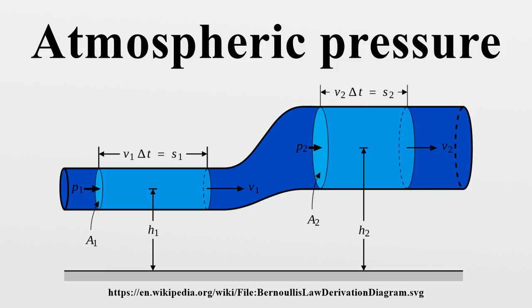The graph at right was developed for a temperature of 15 degrees Celsius and a relative humidity of 0%. At low altitudes above the sea level, the pressure decreases by about 1.2 kilopascals for every 100 meters. For higher altitudes within the troposphere, the following equation relates atmospheric pressure P to altitude h, where the constant parameters are as described below.